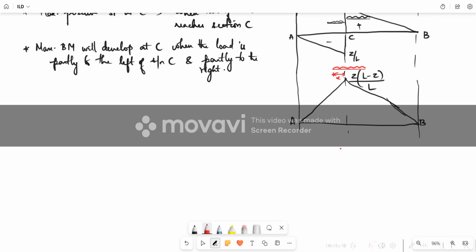Okay. So accordingly, I can draw the ordinates here and this is the tail end and the head end is also creating an ordinate here. So I will consider this as y1, let this be y2, and at the middle of course you will have the maximum ordinate which let us consider as yc. Okay, so the distance will mark here again, this is x and this is d minus x, and from A to C this one is z. Okay. Now, let us derive it. So, let the position of load be as shown in the figure.